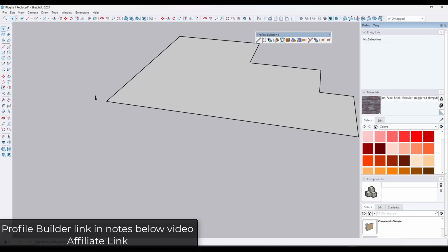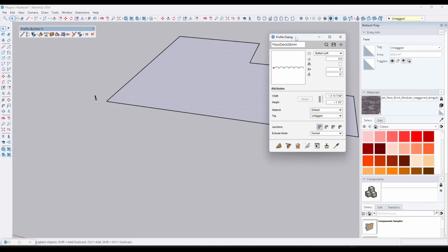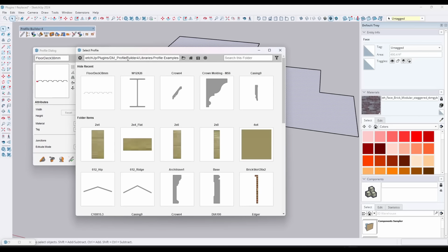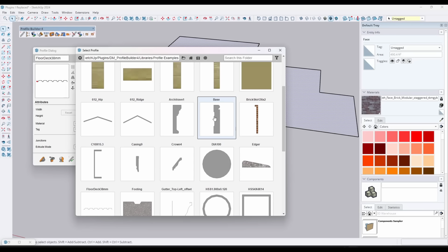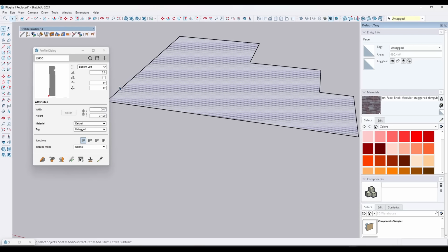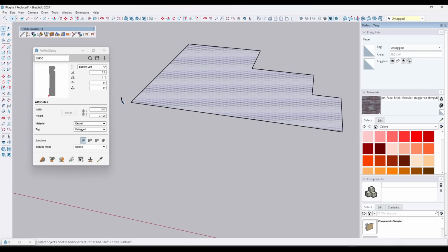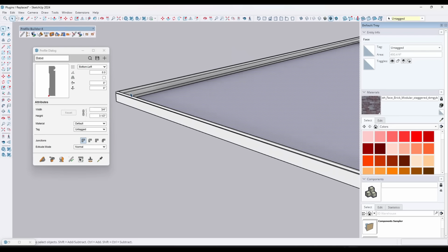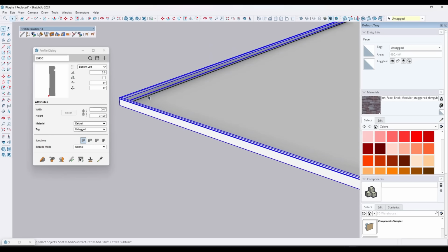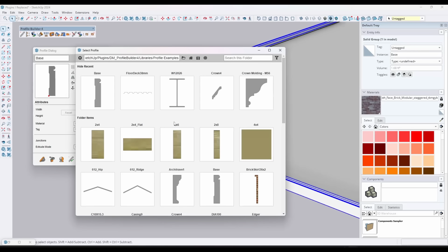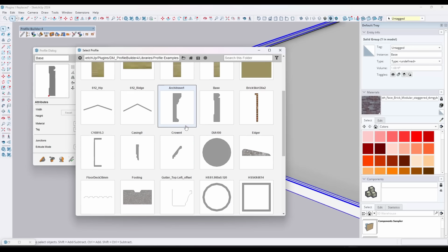It's super in-depth, but basically it's a tool designed to help you manage your different profiles of things that you want to extrude in SketchUp. So you can use this to generate things like flat profiles and then save them to a library, but then I don't have to align anything to surfaces or anything like that. It's got a built-in Follow Me tool, which will extrude along paths, but it also has the ability for me to select those profiles and swap them out with other profiles.